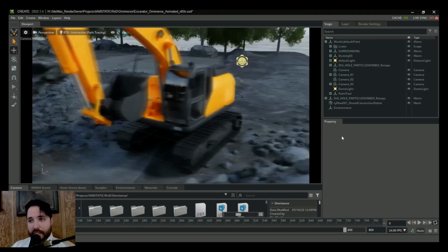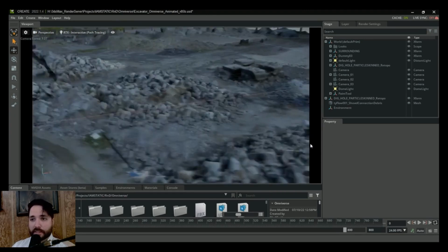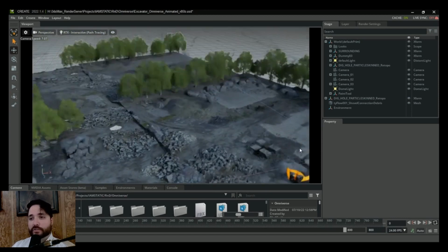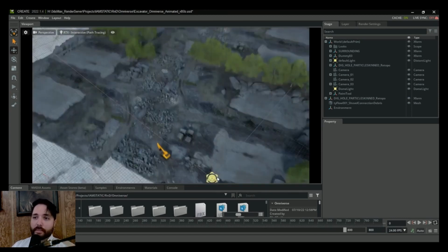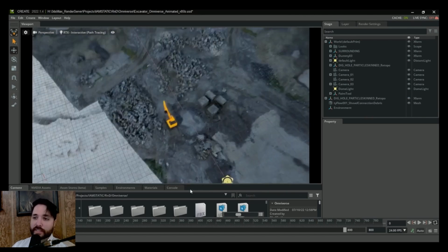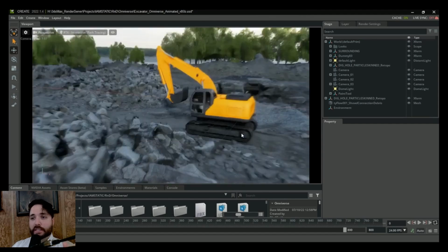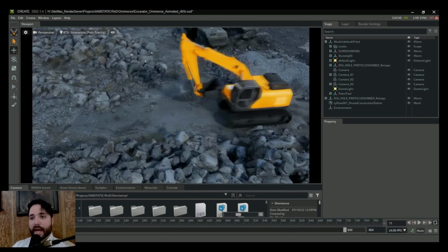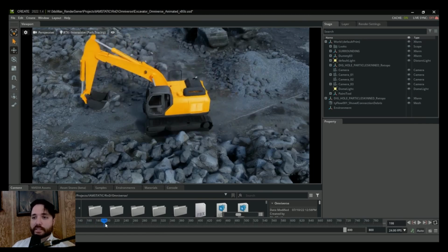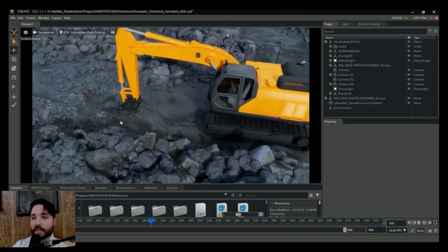I converted the FBX files into USD, and then I simply dragged my Alembic files into the scene as well. My Alembic files were also fairly large for the scene. For example, in just the scene alone, the rock sim was 110 plus gigabytes, so it can really slow down your scene quite a bit, especially when you're scrubbing through your timeline to see the animation. Again, having an SSD drive definitely speeds things up as it helps Omniverse to read larger file sizes.